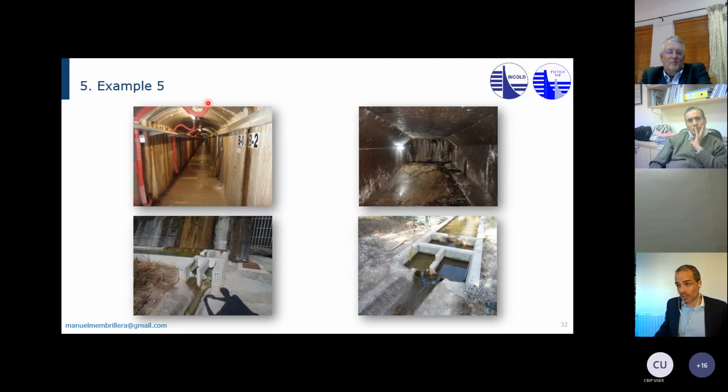So we're connecting this water, and in order to prevent a lot of carbonate deposits from building up, just look at this pipe, how it's turning here, and look at this inverted siphon here, see? So this turn in the pipe is making that this water, which is dam body drainage, as opposed to the one from the foundation. So this is from the dam body. Thanks to this turn, the air from the gallery is not going into the pipe. And this is preventing a lot of carbonate deposits from building up here.